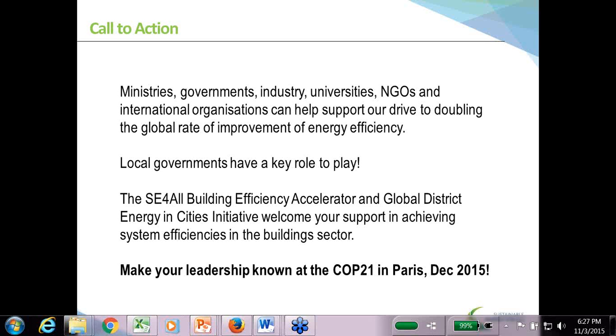After speaking from the city of Rotterdam, I think meters are very important because I think it was also said by Eva, it's very much also about behavior. And having meters gives you insight in the behavior, because we found in the Netherlands that the theoretical reduction of energy use of a building that has been improved was much higher than the real improvement. So what I'm trying to say is that if you insulate a house, you expect the amount of energy used to drop dramatically. But what we saw is that people were using actually more or the same amount of energy because they thought, oh, my house is insulated now, I can heat up my bathroom and my kitchen, while they did not do it before. So having understanding of what kind of energy you use really helps.